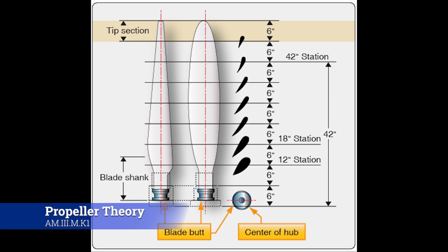Okay, so this is what they're calling the propeller blade elements. What I want you to see here is the aggressiveness of the different parts of the blade. The blade is going to get thicker the closer it gets to the hub, and then thinner as it goes farther out. But also the aggression in the twist of the blade is going to hit its max, I guess, midway through the blade, because that's really what's doing the majority of the work.